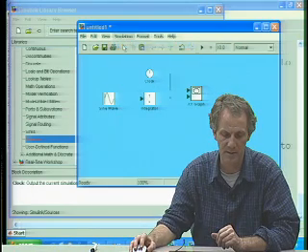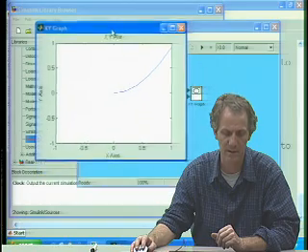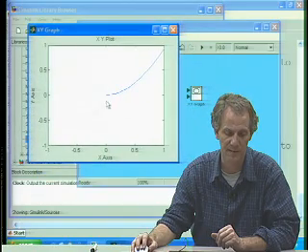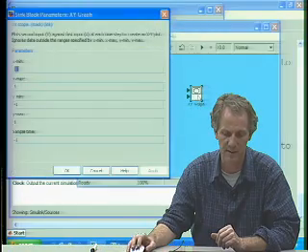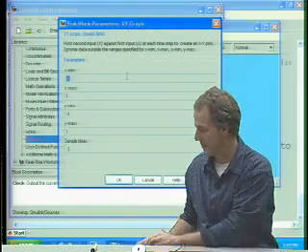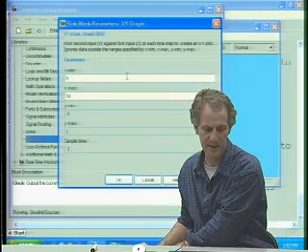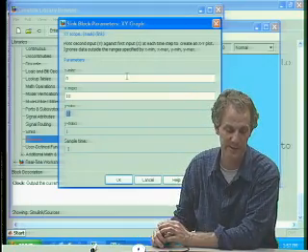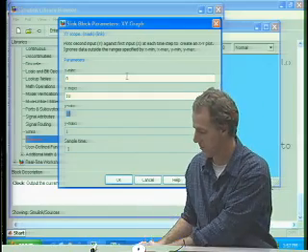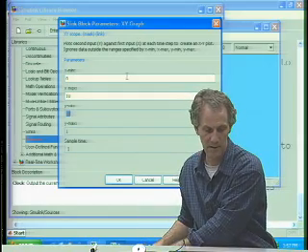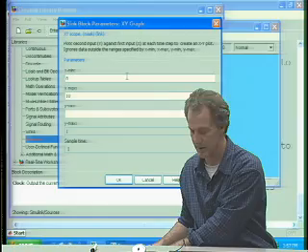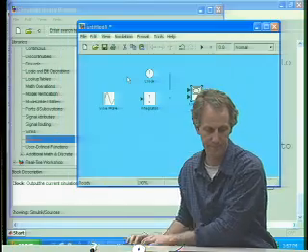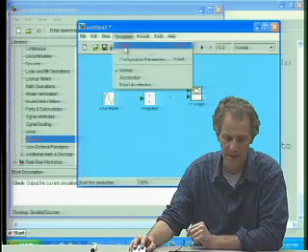And so I'll start it, and we probably won't be able to see very well because I didn't set the graph limits. So we're just seeing a tiny piece of the graph. Let's double click on XY graph. X is my time, so I'm going to start at 0 and go to 10. It didn't automatically scale this, which was kind of an annoying aspect of this graphing tool. And my Y value, I'll go from 0 to 4, I think, is what I want. Let's say -2 to 4. And then start it again.